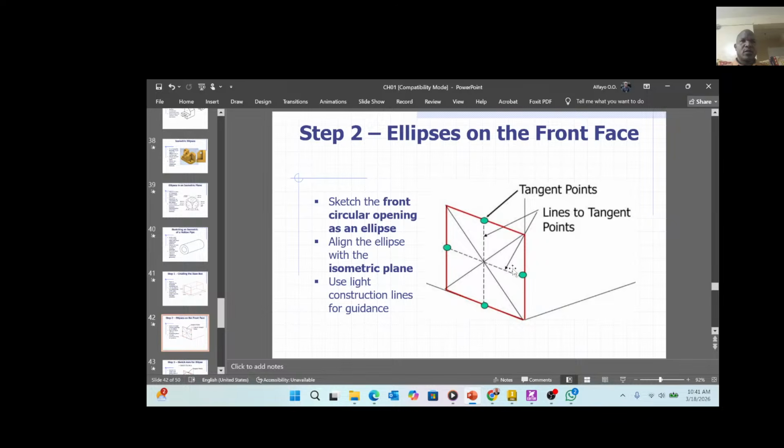Remember the tangents, we talked about the tangents, the two of these, and also the diagonals, the major diagonal and the minor diagonal. I want to believe that you remember how I told you. Later, you can just join these diagonals from here to that one. For this one, along the major diagonal, draw from this point to that point with a straight edge. The point of intersection here is where you use your pair of compass, open it, point it at the middle of where it intersects here with a span radius from this point up to this point, and draw an arc. We'll come to that one.